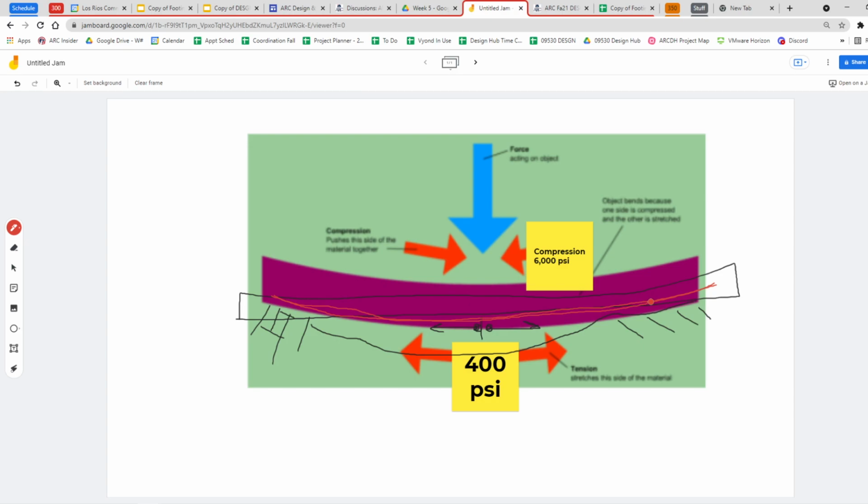So it's not going to crack and break. And so the concrete crack runs into the rebar, and the concrete is actually gripping the rebar. So even if it does crack a little at the bottom, it won't propagate over to the top. So that's what rebar does.